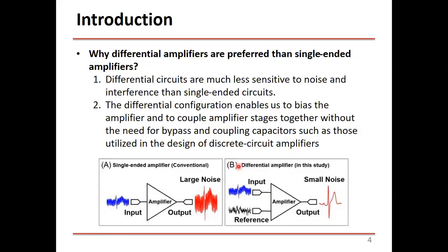But in the other scenario, if you have a differential input with two sensors picking up the signal, one is the ground, for example, and one is for the signal. Usually when they measure the heart beating signal from a patient, they put one electrode on the heart and the other one far away, like on the leg or the arm, to be the ground, the reference.